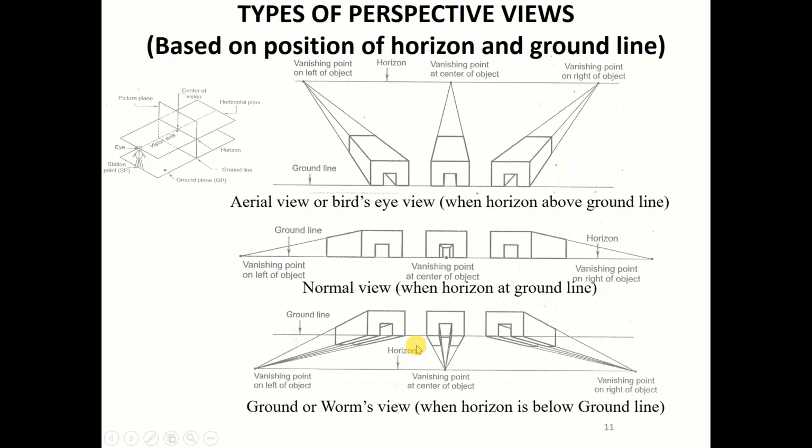The third case is when the feet level is here and the horizon level is on the lower side, so the eye level is even below the feet level. In this case you can see the front face, like in the other two options, here you can see the left face, and you will also see the bottom details of the object.